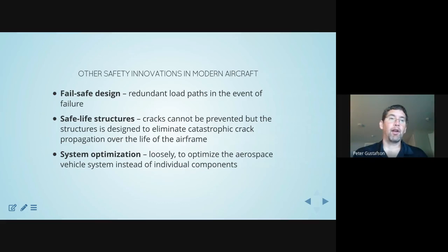Wing sweep tends to not allow you to decrease the wing area, which means ultimately that you become constrained with your lift coefficients, and you're not necessarily able to fly at optimal lift coefficients in all regimes of flight. If you're able to morph the wing and resize it in real time, then that allows you to find better lift coefficients. Of course, if you're at optimal lift coefficients, then you are improving your efficiency.